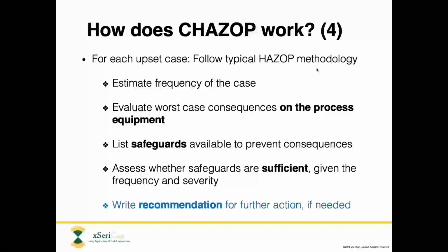First one, what if the AC power feed is lost? Second one, what if the I/O card fails high or fails low or fails with frozen output or maybe some other kind of output such as fluctuating or noisy output? What would happen if there's a network switch failure? So those are all what if questions.